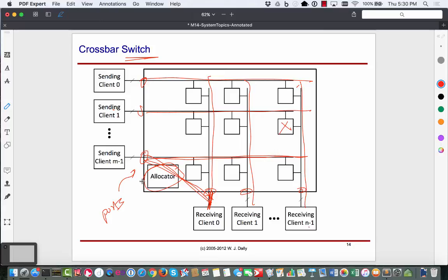If you ever look at a photo of an FPGA die, you would see that it has lots of pockets of logic gates which can be programmed, and then wires running in a Manhattan grid-like fashion, with switches in lots of places. Then I can take a piece of hardware and map it to one place, another piece of hardware and map it to another place, and I can tell my EDA tools, these guys need to talk, and they arrange everything from that point on.